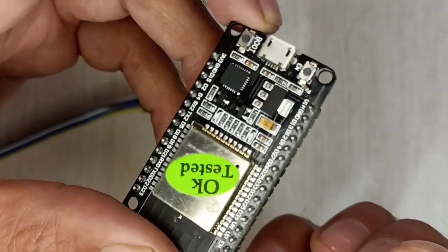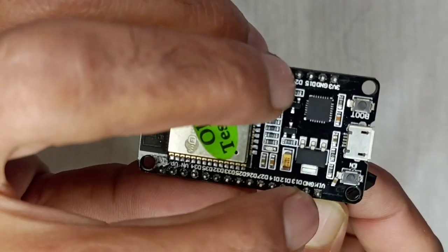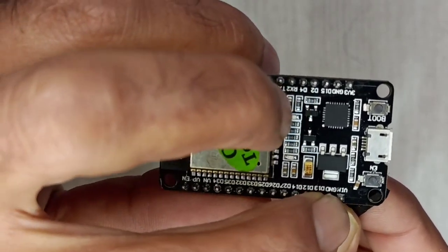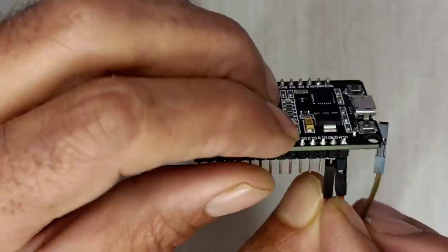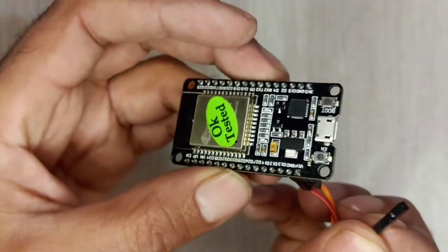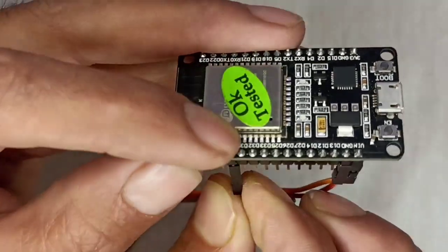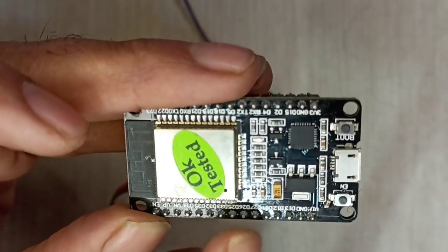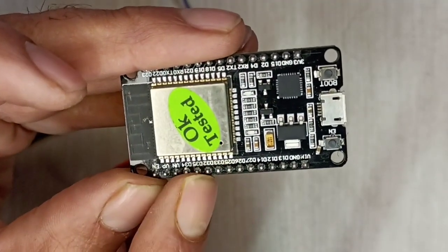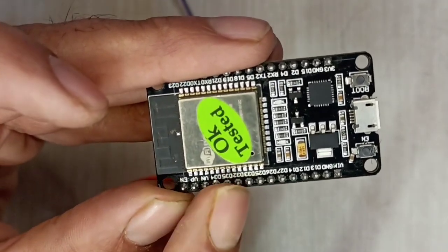So now I'm connecting this VCC pin to VN. VN is the 5 volt pin here, in the ESP32 the output here is 5 volt. Then we are going to connect this ground to the ground, and then we connect this pin to one of the pins of the ESP32. I will choose pin 34. Remember one thing, in the ESP32 pins 34, 35, 33, 32, 26, 27 are the ADC pins, analog to digital pins. You can use your analog sensor here as well as your digital sensor. Okay, so now the setup is complete.